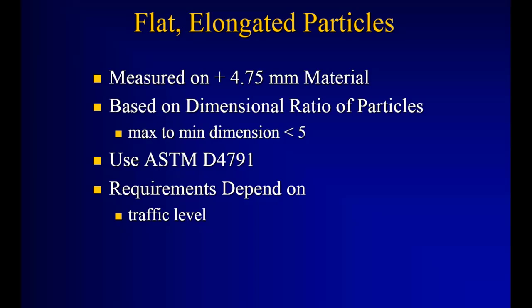as well. And even in South Dakota, where, as I mentioned, there's three kind of quarry sources, far west, far east, and northeast in South Dakota, you very rarely, in fact, the only time I've seen a test that failed was with quartzite in the Sioux Falls, Mitchell area. And that's a quarry or shot rock material, and the flat and elongated was actually created by the crushing operation. Using the impact crusher basically in secondary mode during crushing and screening.